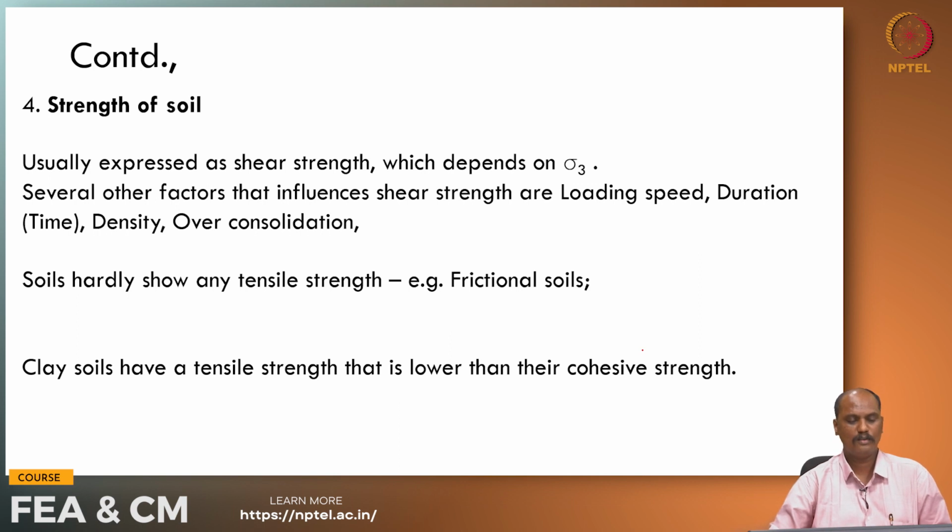When it comes to the strength of soils, usually we mean the shear strength of soils. The shear strength is mainly dependent upon the confining stress level, what we call sigma 3, which is a very important point to note. Several other factors that influence shear strength are loading speed, how quickly the soil is loaded, the duration for which the load prevails, and the density and over consolidation, or OC, behavior.